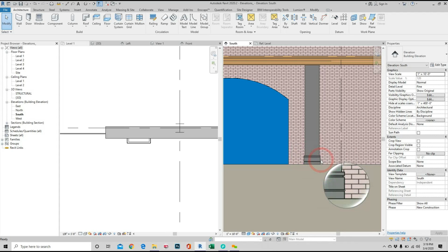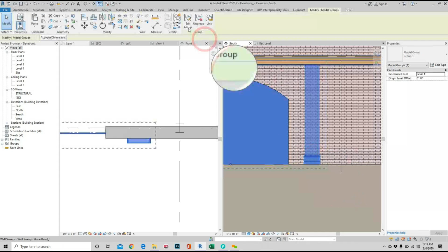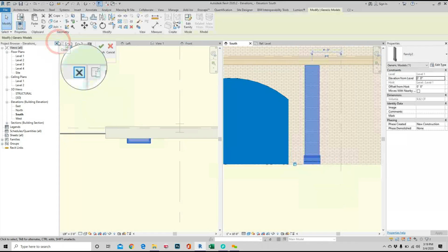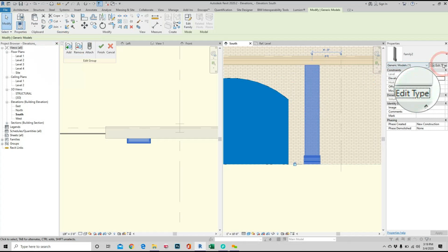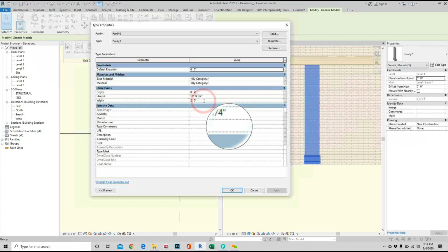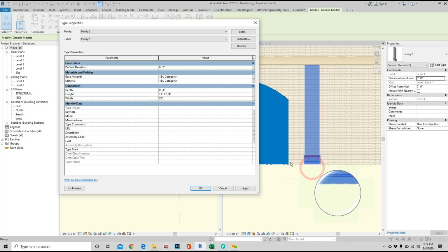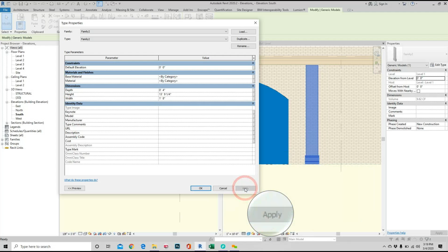Yeah, but the width, and the depth, because I locked it to the pilaster, remember? I fitted that? Good. Thank you for the reminder. So I'm going to go in here, and I'm going to click on this guy and let's say I changed my mind. It's not 2 feet. I'm going to do 20 inches. I can go to edit, click on my 20 inches here now, and that profile here should move with it. There it is, 20 inches. I don't have to worry about it.